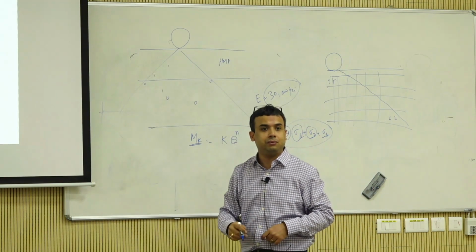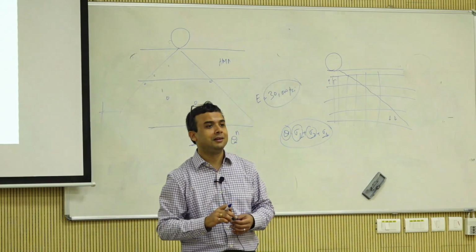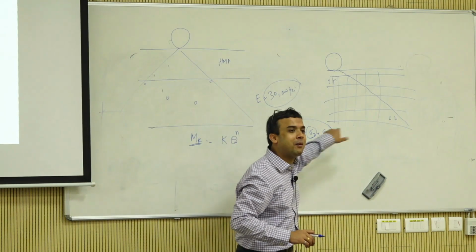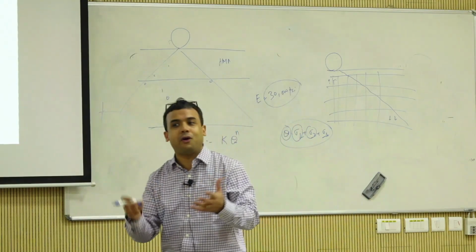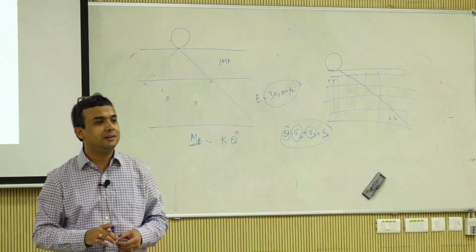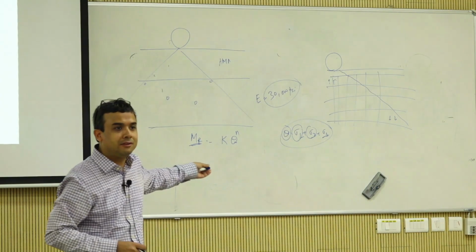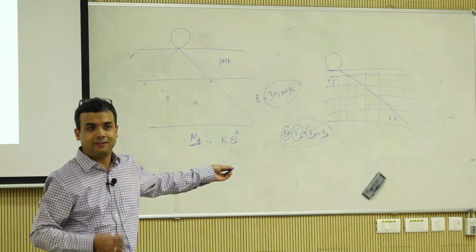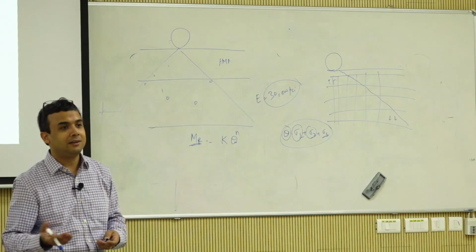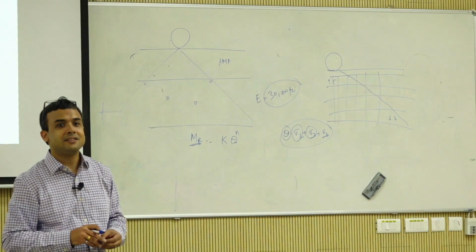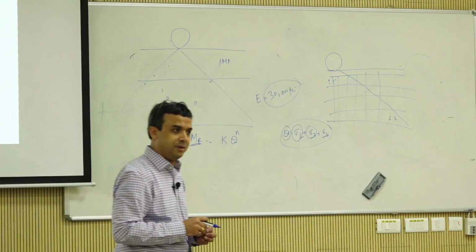But I have a question. I know what you're asking. I'm going to ask that question, so you can't ask me. How do you get sigma 1, sigma 2, sigma 3 in the very first place? To run your forward analysis, what do you need? Modulus. I thought you were determining the modulus. That's what you're asking, right? So what are you going to do now? Seed modulus, right? So let's talk about that a little bit.